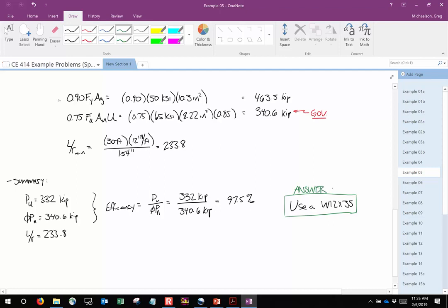The only thing that might be a little mysterious is where did the dead load and the live load come from? There's a simple answer. It comes from structural analysis. Y'all remember how to analyze a truss? Analyze a truss, you got some dead load and some live load in that truss member, 1.2 dead plus 1.6 live, bam. I'm not making you analyze a truss because I have done that before. I have made you do that before. I know I have.